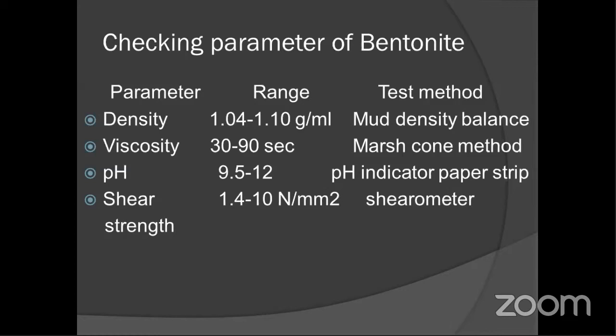The diaphragm wall excavation, the grabbing, will be done with bentonite mud circulation to prevent collapsing and caving. Sometimes while doing the excavation work, some caves get generated. While putting the concrete, the wastage of concrete will then be more, and we cannot afford that. So we should go for this.